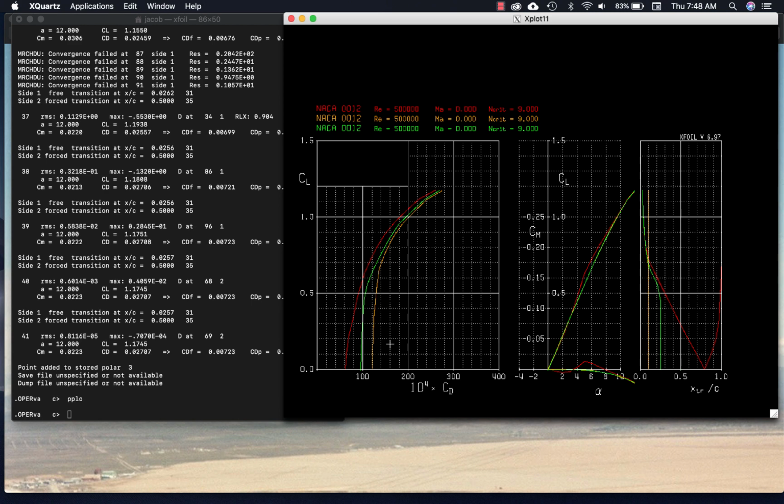As I mentioned, however, for much larger aircraft, let's think of an airliner which has a very, very large wing and is moving at a pretty good clip, regional, full-scale transport, wide body doesn't really matter. A fighter aircraft which has a smaller chord length on its wing but typically a higher velocity. Those critical Reynolds numbers, if you say, hey, we're in the range of 500,000, that's still going to be really, really close to the leading edge. So you're going to trip the flow anyway. Most of your boundary layer is already going to be turbulent throughout the entire flow.